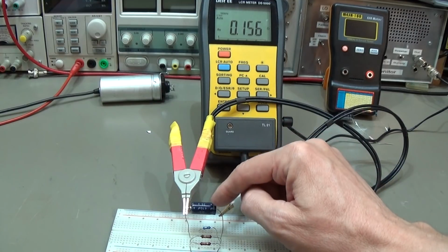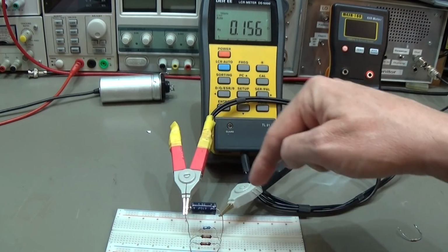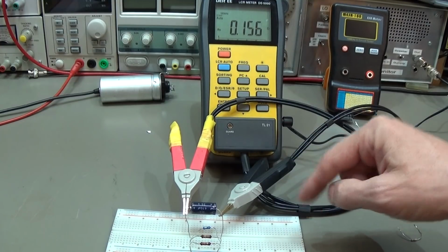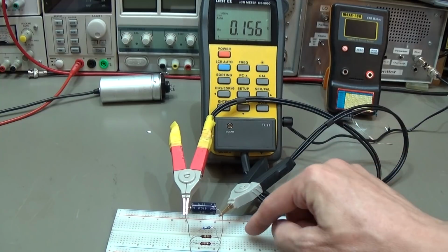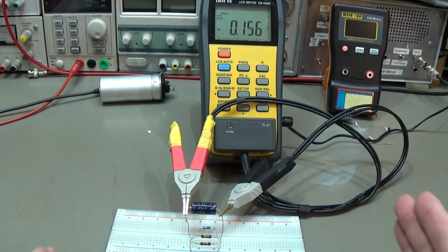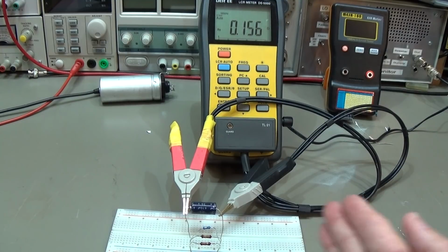If you have a couple of capacitors in parallel, then you would always read the lowest impedance, and you do not know if one of the capacitors which are in parallel is good or not, because you wouldn't really see the high impedance if more than one is in parallel.